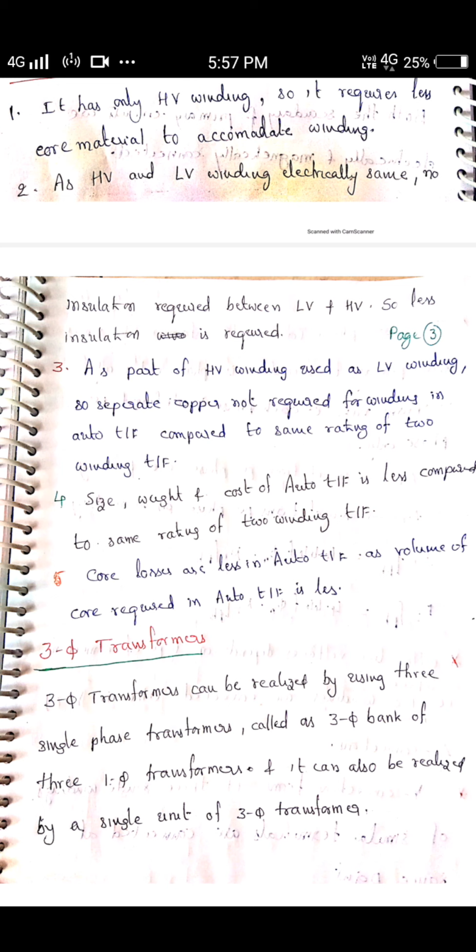Now come to three-phase transformers. Up to now we discussed single phase. One AC supply given to primary, secondary you are getting single phase supply. Now to prepare three-phase supply, we need how many windings? No doubt we need 3 windings. If you take 3 single phase transformer banks and interconnect them, we can form 3-phase supply. Otherwise, by placing 3 windings inside, we can prepare 3-phase transformers.